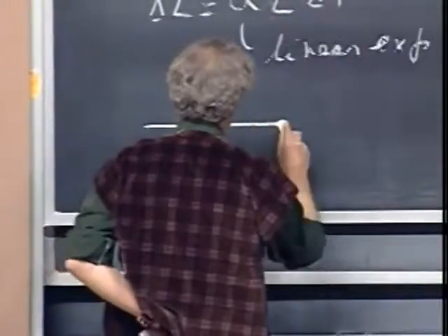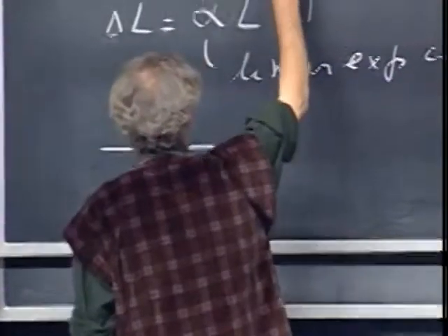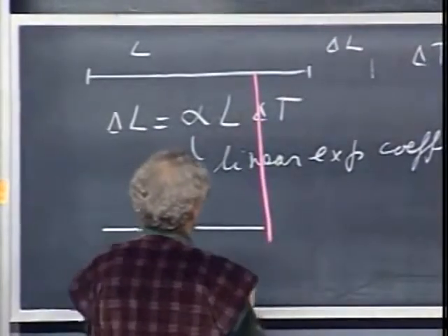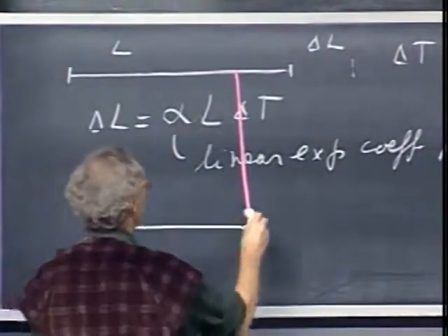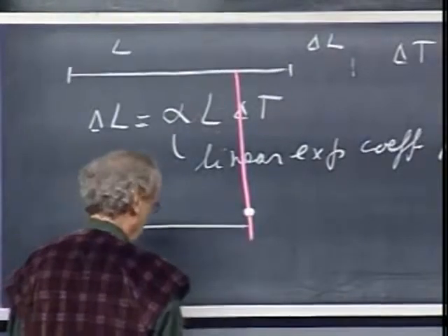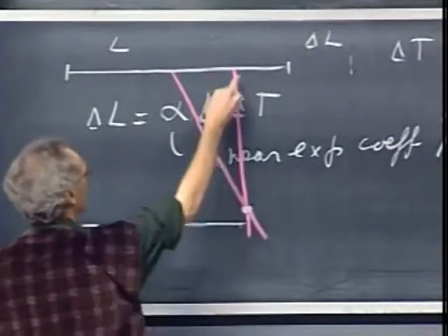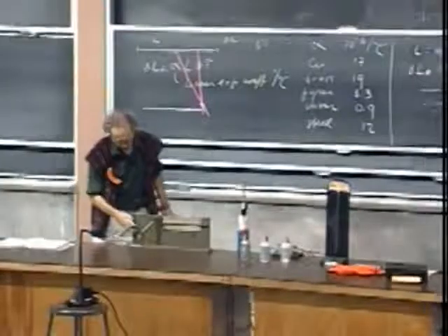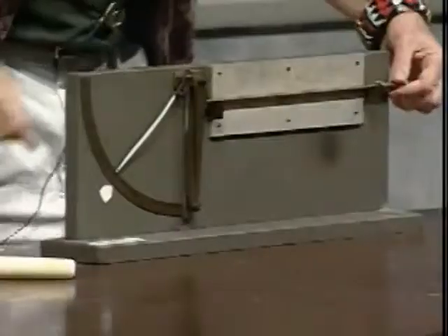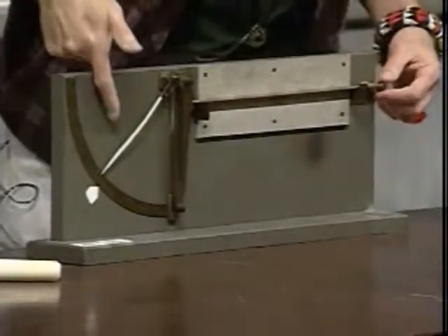The way we do that is we have some kind of an amplifier. If this is the rod, and I put a hand here and pivot that hand here, then it's easy to see that if you push against it here, this hand will go like this. So very little extension here will give you a large extension there. We do it twice, so we have two levels, and that is this arm. I have here a set screw, and I can move the bar in this direction. I'm not making it longer, but I can move it, and you will see what effect it has.